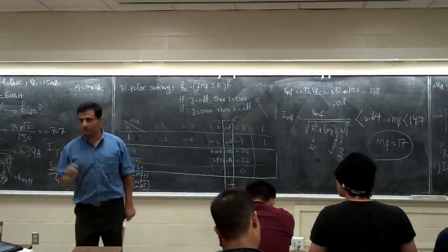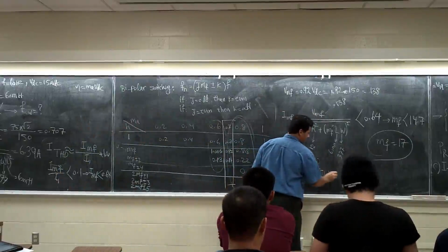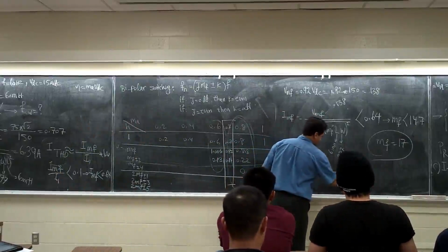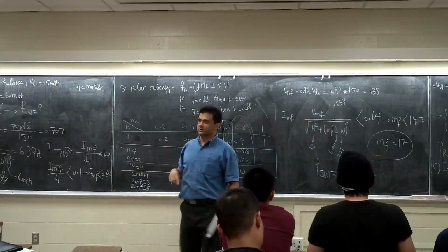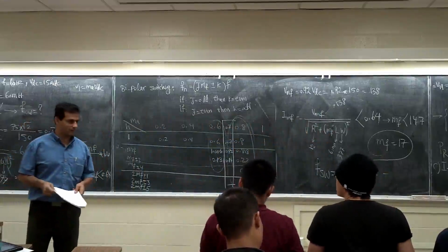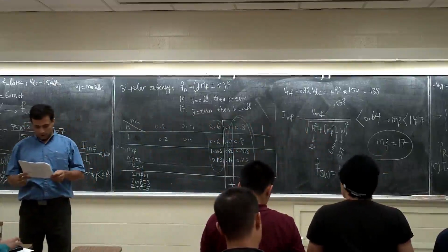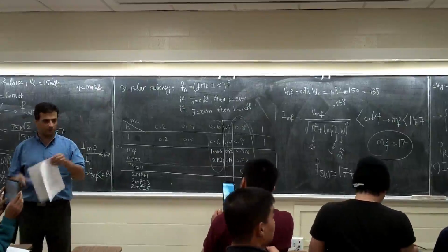So, how much is the switching frequency now? FSW, 17 times 60. Go double check the THD. For sure it's going to be less than 10%. Okay, we're going to stop here. I can't explain more, I'm going to finish what I want.